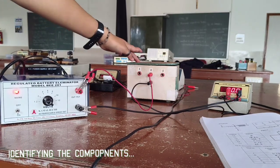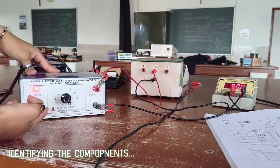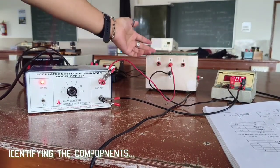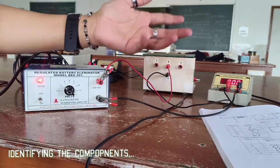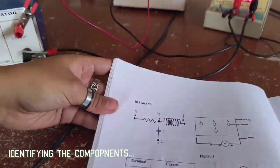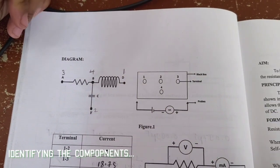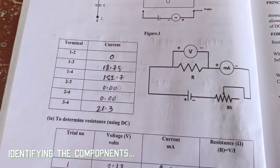Here we have our black box, this is the milliammeter, and this is the regulated battery. In the first step, we have to identify the different branches of the black box. We need to know the three components' positions. In this diagram, we have the resistor, inductor, and capacitor, but in our black box they could be in any order. So we need to figure out the order, and for that we have to set up a very simple circuit.